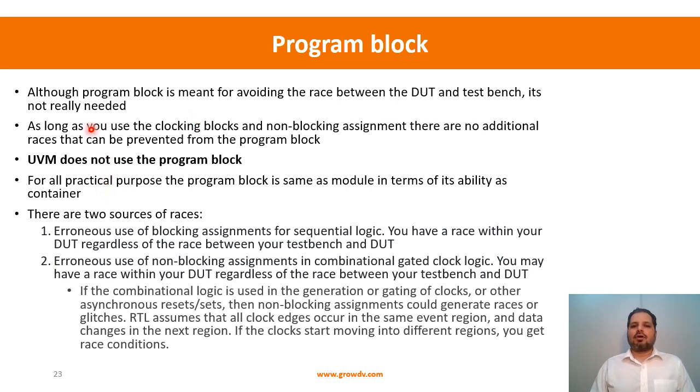As long as you use clocking blocks and non-blocking assignments, there are no additional races that can be prevented by the program block. That's what has been concluded, and that is the reason, if you look at it, that UVM doesn't use the program block. That is what seals the fate of the program block. For all practical purposes, the program block is the same as a module in terms of its ability as a container, and also suffers from the same problems that a module can suffer in terms of race.